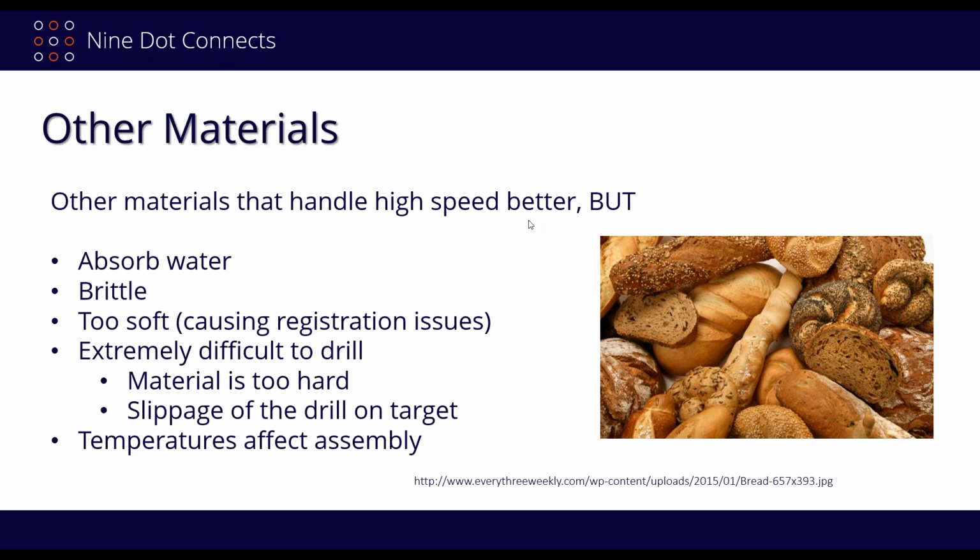So with FR4, if you can't use it, a lot of times you want to substitute other materials, but what you generally find on the PCB side of things is you mix and match materials. You don't just say, I'm going to use this one from Isola and only this one, because you're probably going to have some problems with it. Instead you mix and match materials so you compensate for the things that become problematic. That's the same thing that happened in the baking industry. With all this gluten-free stuff, if you look at the ingredients now, you've got 4 or 5 different flours mixed together, so whatever is a deficiency in one flour is made up by the other. So hopefully you get the idea of the analogy I'm trying to put across.